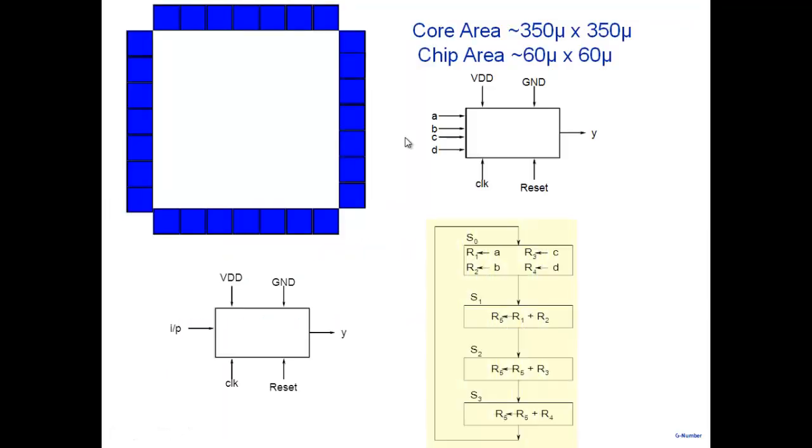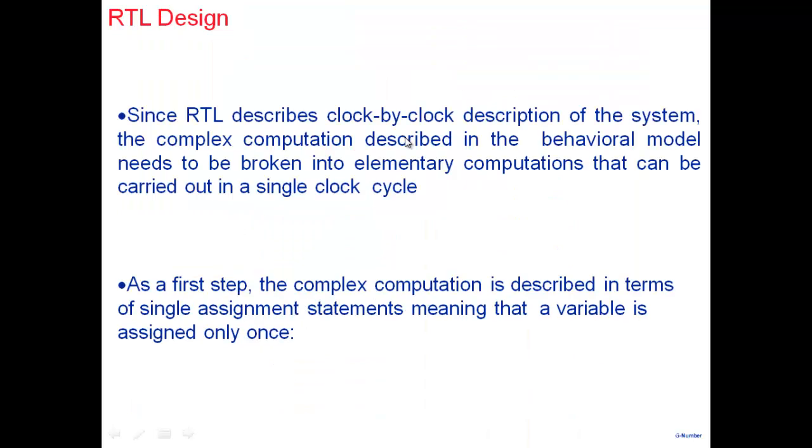Okay, so coming back, finally what we said was, as I said, we can take a problem intuitively, look at it, and break it up into a state-by-state description of the computation. And after doing it, one should examine it and see whether the utilization of registers and adders is proper or not, and maybe try and optimize the RTL description. I was also saying that instead of doing it intuitively, there is a more formal method of carrying this out.